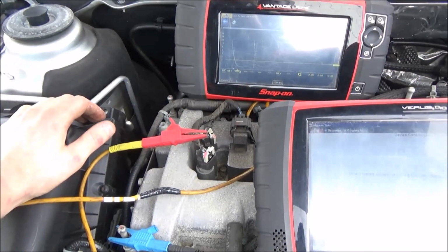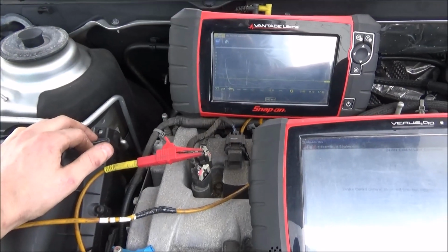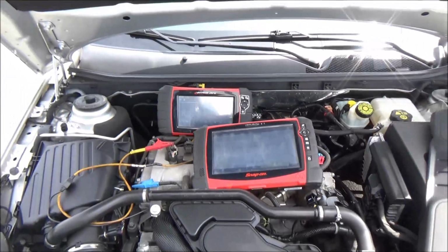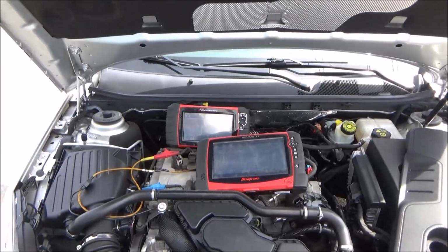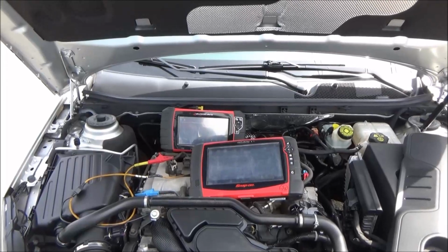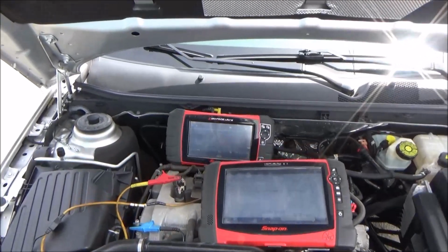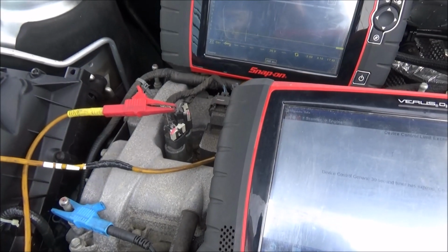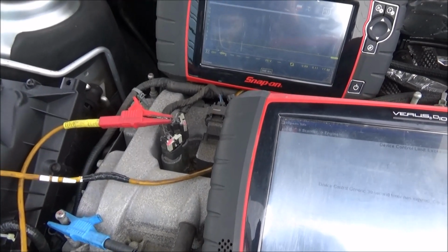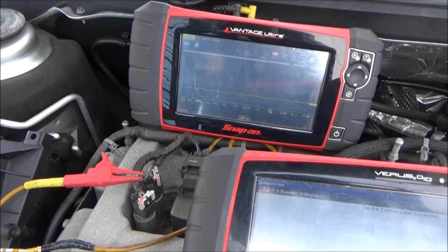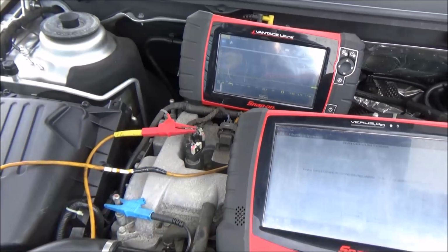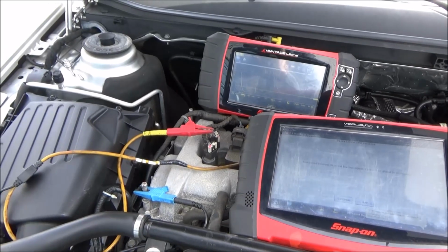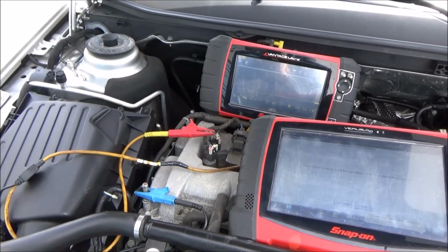Now what I want to show you guys is my favorite method of testing these solenoids, and what I've found to be pretty reliable and condemning. And that's going to be a resistance check through the solenoids. So what we'll do is we'll take a resistance measurement of this intake one first. This is the one we're pretty sure is bad. And then we'll do one on the exhaust valve. We'll compare the resistance values, and I'll show you guys what we come up with there. So let me get that all set up for you.